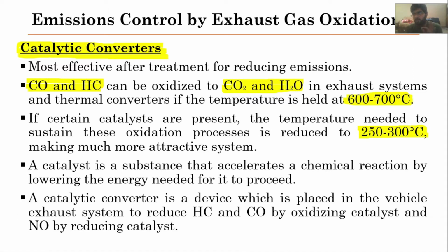So we do not require very high temperatures. We do not have to rely on the amount of energy released when carbon monoxide and unburned hydrocarbons are converted into carbon dioxide and water vapors. So all the disadvantages and limitations of the thermal converters are overcome by the use of the catalytic converter.